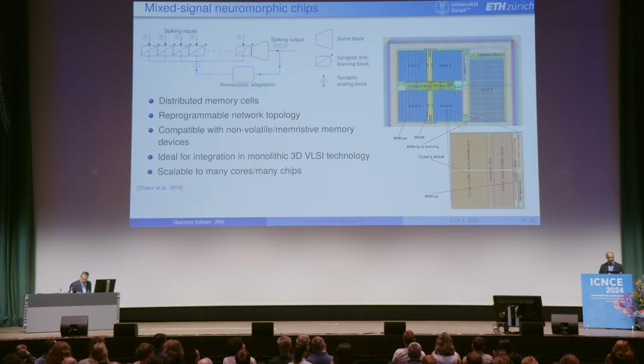In fact, if you zoom in on any one of these pixels, which are these neurons, and look at the ratio between analog and digital circuits, you'll realize quickly that the digital circuits take up most of the area. More than 80%, I think 86% of the area is for SRAM and TCAM cells that contain the address of the neuron that each synapse is listening to.